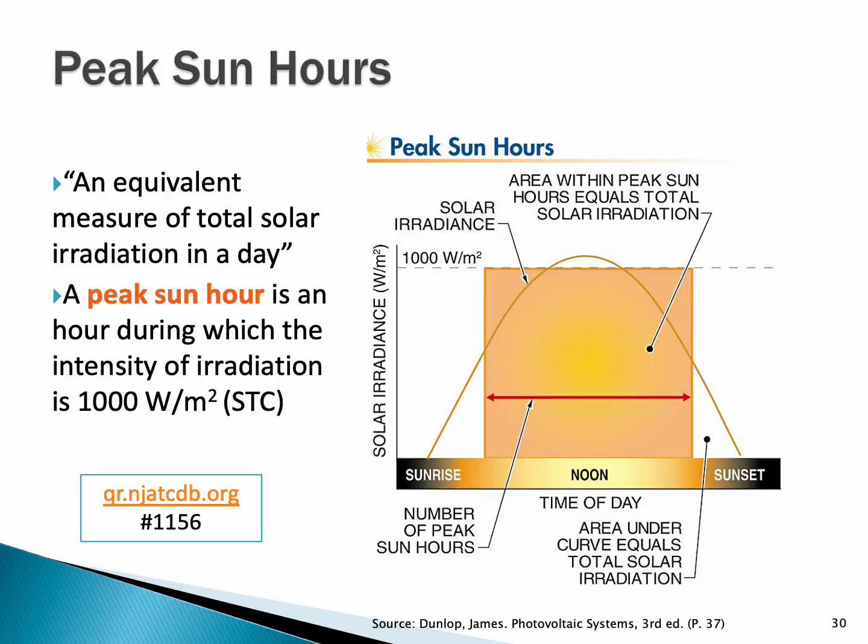And as time goes on a clear day, we're going to get longer and longer lines representing more and more energy being produced at that particular moment. And so if we add that all up together, we get this cumulative peak sun hours, or we have an equivalent to, say, 4 sun hours per day, or 4,000 watt hours per day, kilowatt hours per day, cumulative.